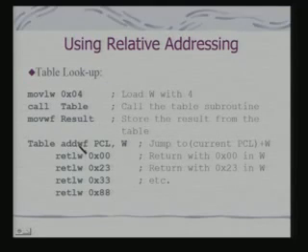This instruction, ADDWF, is a routine instruction in the sense that it can be used with any register, but here it is interesting because it is using PC, the program counter. So, the current PCL, the lower part of the program counter, is used as an operand. Now, this feature is not typically supported in many instruction sets. That is, you really cannot use PC as an operand in an instruction, but PIC provides support for this kind of instruction. So, what is it doing now?